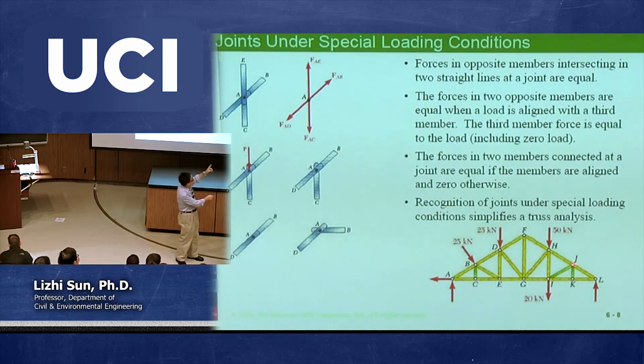So in other words, in terms of forces acting on joint J, there are only 3 forces, because Fjk equals 0. There's a member there, I agree. It's made of wood, for example, but it does not contribute to the equilibrium equation because that has to do with the forces. So you're still having only 3 so-called non-zero forces acting on joint J, and 2 of them in one direction. Then the third one is what?